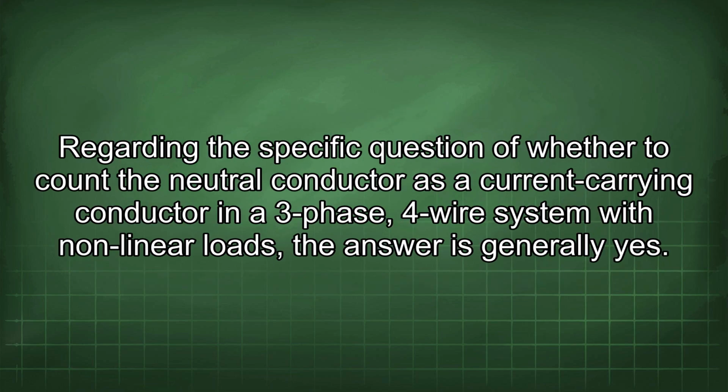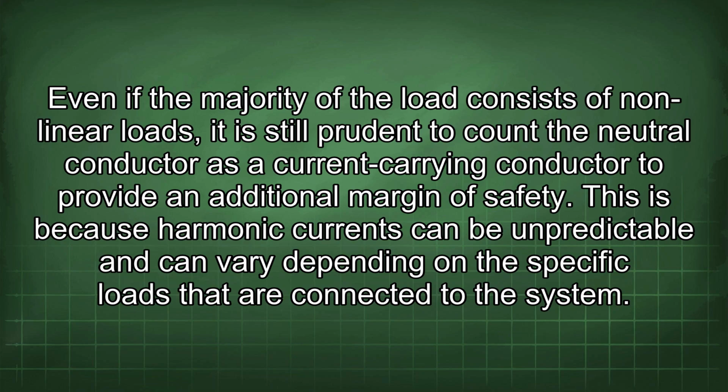Regarding the specific question of whether to count the neutral conductor as a current-carrying conductor in a three-phase, four-wire system with nonlinear loads, the answer is generally yes. Even if the majority of the load consists of nonlinear loads, it is still prudent to count the neutral conductor as a current-carrying conductor to provide an additional margin of safety.